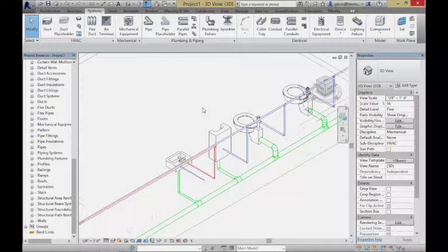So, for example, on a large hospital project where there's pipe running every which way to handle all the different systems, for an individual room you may figure out every last elbow, every last transition, exactly where they need to be running down to that last inch, because it really has to be controlled at that level. What will tend to happen in a scenario like that is you may figure it out for 1 or 2 rooms, and then those rooms will be copied and arrayed around. So the degree of control you put in depends on how much control the finished product needs, and some jobs they really do care about every last inch, and you'll need to do it at that level. So it just varies.